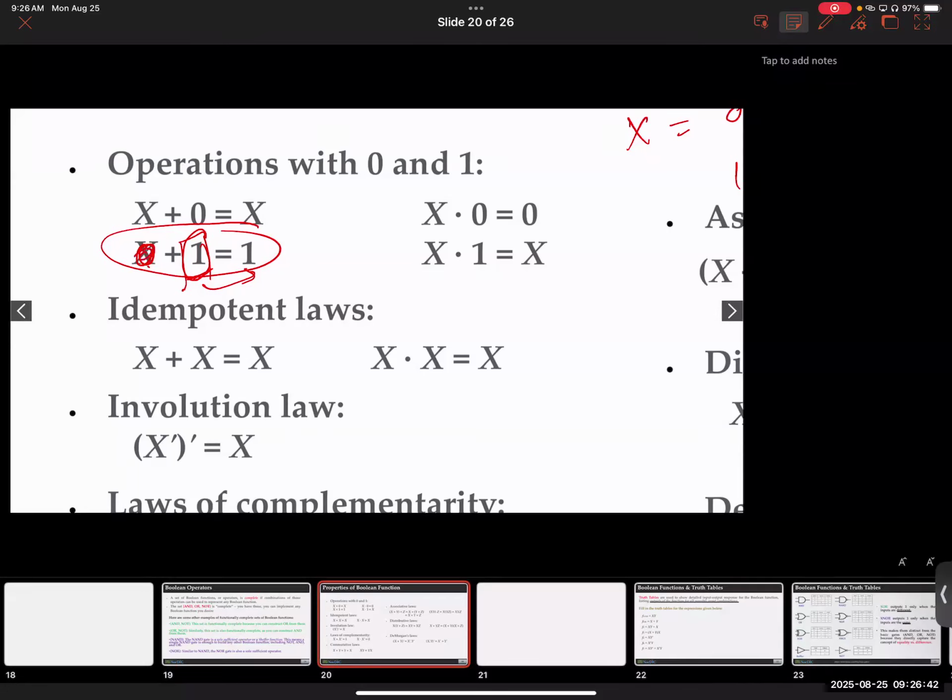Okay. And what if x was 1? Well, even better. You still get 1. So all you have to do is plug in the binary values. And there are just 2 options, as you see. Put in 0 and see how this looks. Put in 1 and see how this looks. Given that you already know the truth table for or, and, and invert, these three are the fundamental concepts. You agree upon these three truth tables, and then everything else will fall in place.